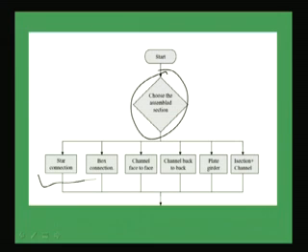Assembled sections in our software, which has been developed by my students, that are available are: one is star connection, another is box connection, then channel face to face, channel section back to back, then plate girder, then I section with channel. So these 6 types of built up sections we have made in our software. However, n number of built up sections can be made in our software as per our choice. These are the 6 types of sections which have been chosen because they are largely used in the industry.